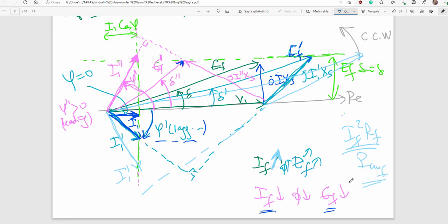There's heating, and as a result here's an increasing armature current. 3 times armature current squared times RA causes some copper losses in the armature, and again there is overheating in the armature.